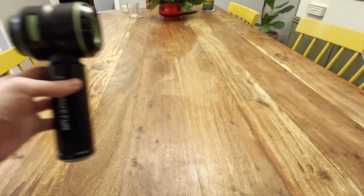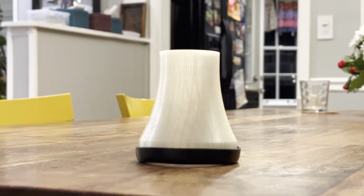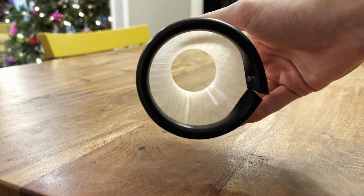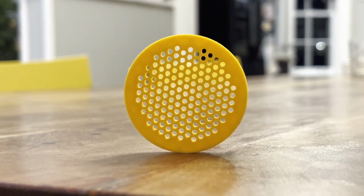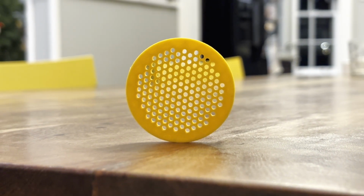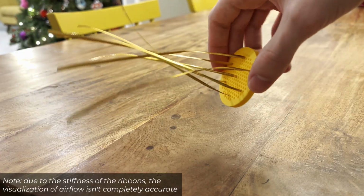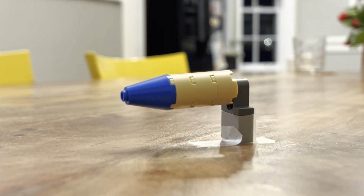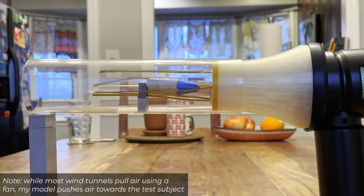I decided to use a handheld air duster to blow air into this clear tube. I 3D printed a contraction section to connect the air duster to the tube. I also glued on this rubber seal to create an airtight connection between the air duster and the part. I also 3D printed a honeycomb filter to reduce turbulence in the tube. I decided to use ribbons to visualize the airflow through the tube, so I attached them to the honeycomb filter. I also built a small rocket out of Legos to put inside the wind tunnel. After putting everything together, this is what the final product looks like.